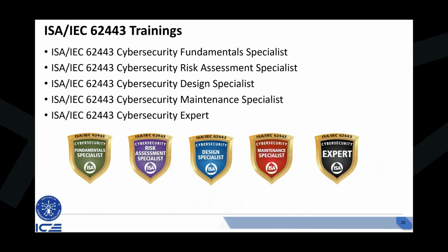Is there a process to do risk assessment for components, not systems? Interesting question. Yes, you can follow the same process for components as well, because when ISA says in the process itself, it says system under consideration, SUC. You can have one component, one PLC as a system under consideration. System doesn't mean the whole DCS. You could have different parts of the DCS, for example, each as a separate system under consideration. There is no restriction as such.